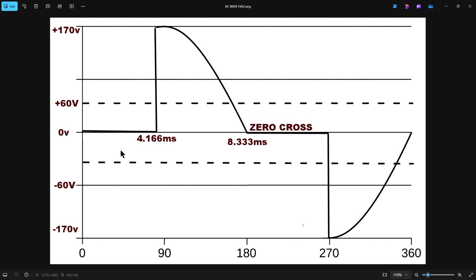So basically, we could use it to turn on the power at any point. So if you had a light bulb that you wanted to turn on and turn off from a low voltage controller, like say an Arduino or some kind of microcontroller or some device, a Triac would be a wonderful device to do it with. Basically, you would apply a voltage to the gate and hold it on as long as you want the light to be on. That would turn the voltage on immediately, as in our previous diagram, run all the way through, and where it would normally turn off, there's a voltage on the gate, so it would keep conducting, and you'd get your full wave, and your light would be on.